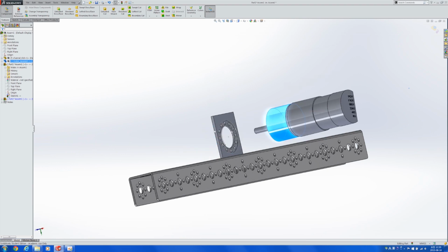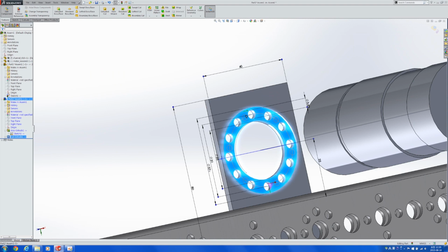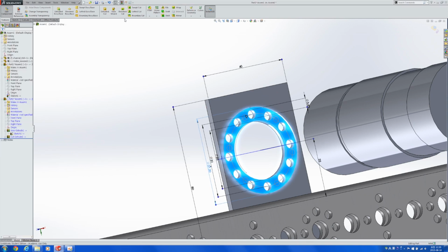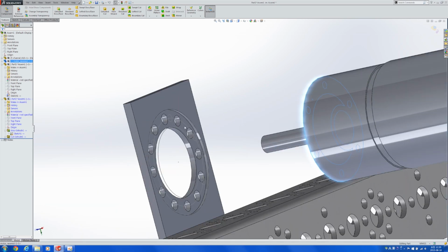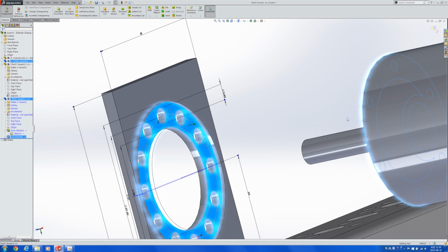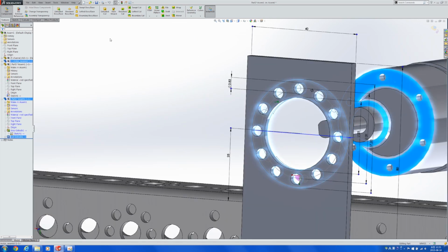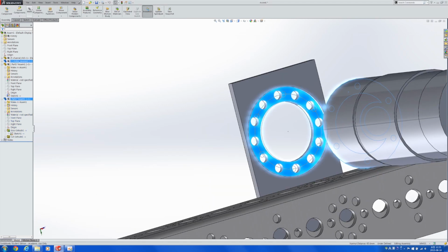And also remember, this is as well another hole, so you will want this to be 37.2 mils like this. And if we connect this here, when you're actually assembling this, the gearbox will go really nicely into this plate, which means it's going to be much easier to align the parts to be concentric, and also to put them in the positions that you desire them to be at.